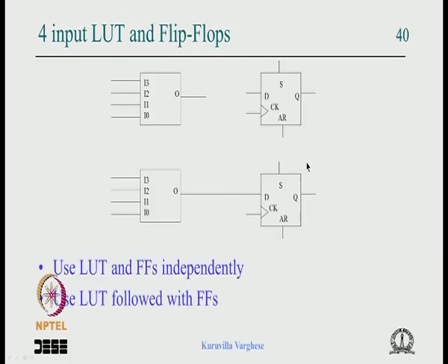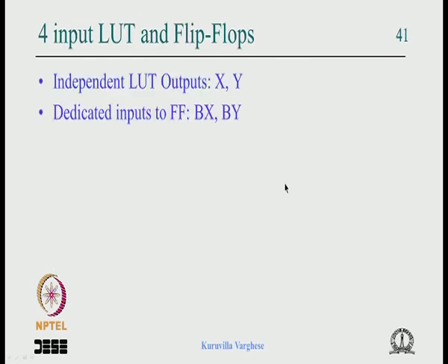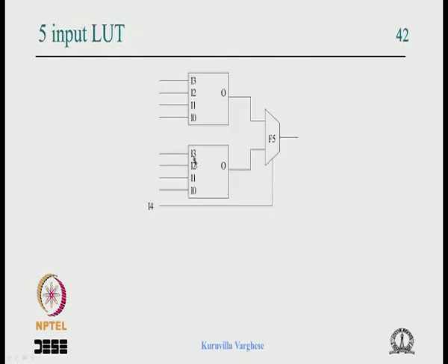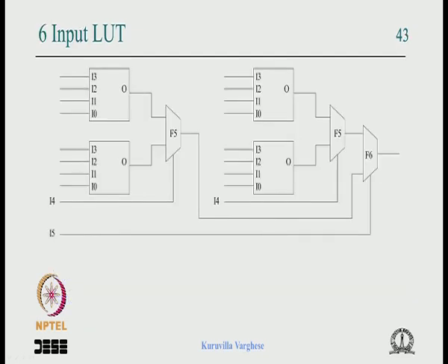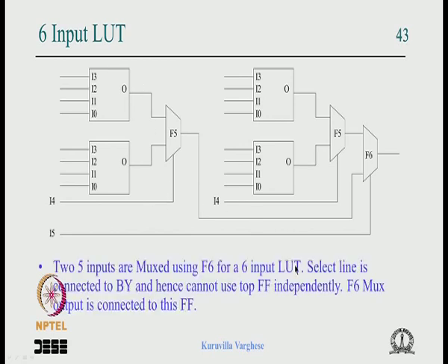I have shown all that using the lookup table and flip flop separately and together, forming the 5 input lookup table from 2 4 input lookup tables, and forming the 6 input lookup table with 2 5 input lookup tables, which consumes all the 4 input lookup tables.